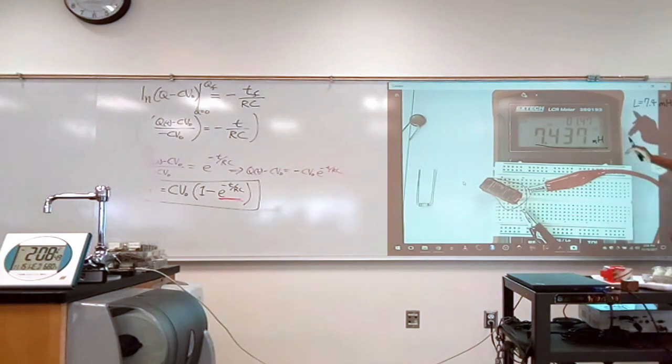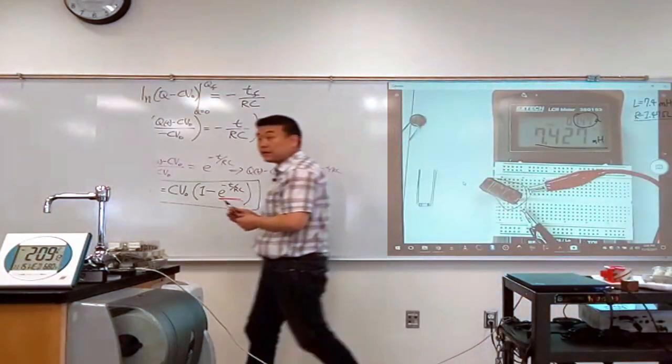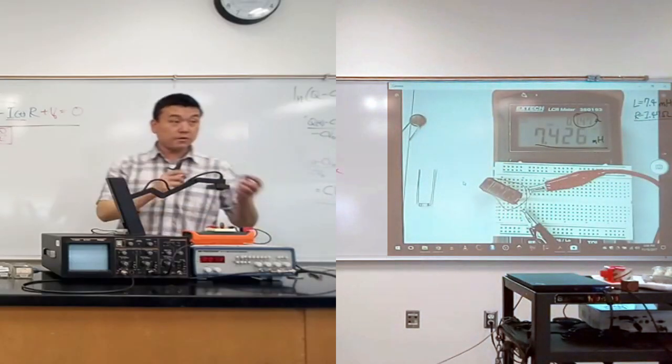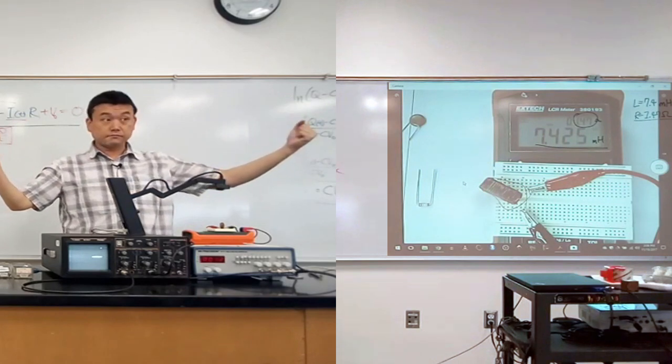And if you look at it really carefully here, or you can do it after class, there's a little omega symbol here. I set it on a mode where it measures the resistance of the inductor. Now, an ideal inductor doesn't have resistance, but it's made up of real wire. So it actually has a resistance of 1.47 ohm, which seems reasonable, right? That's the kind of resistance of wire that you have seen for a reasonable amount of length, like a meter, right?